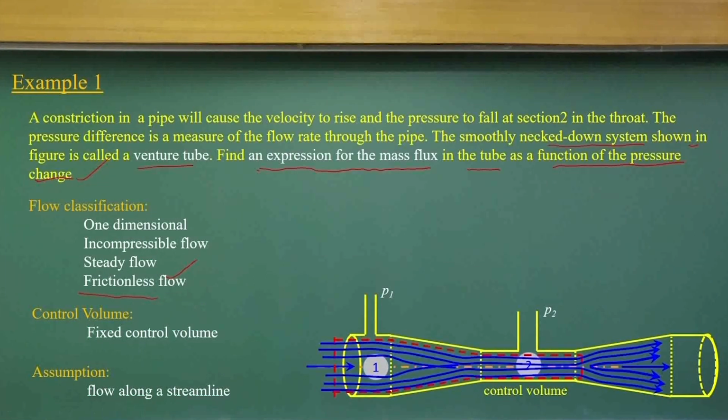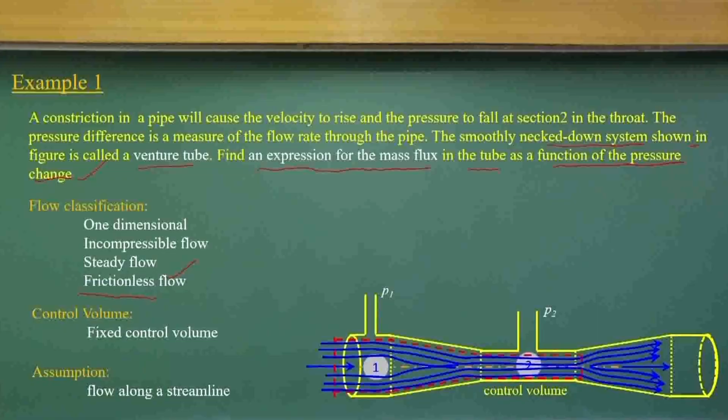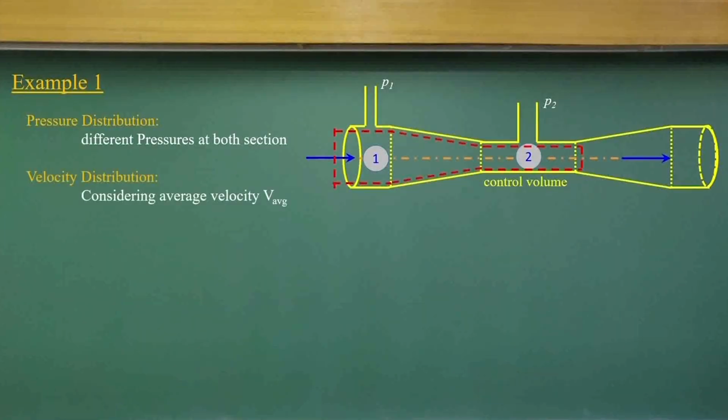The streamline shape could be like this. Okay, there will be converging zones and diverging zones. The streamlines will be converging and diverging. Or if you put in virtual fluid balls, you can track the flow path. The path lines of the virtual fluid balls also could be like this. They will converge, and be more or less parallel in these regions, so there will be no curvature of streamlines in these regions. Then there will be the divergence of the streamlines. So that is the flow structure we get in a venturi tube, and we need to compute it